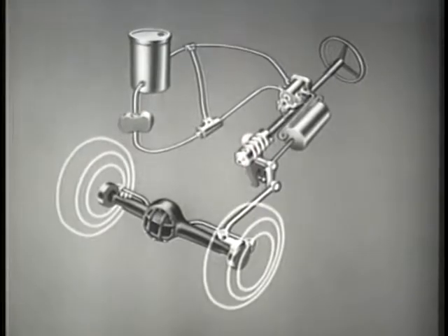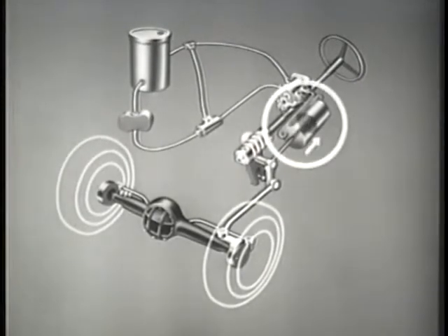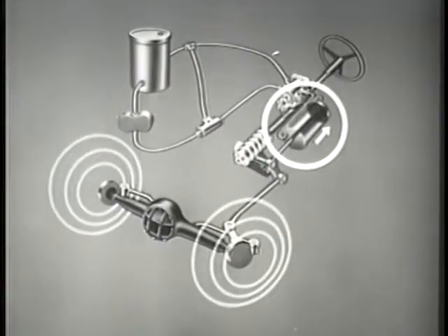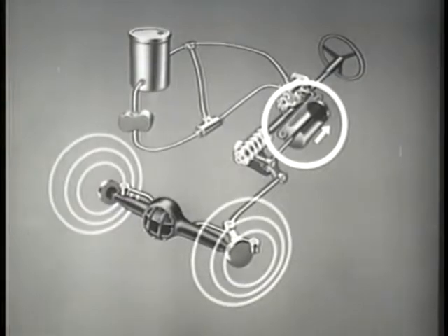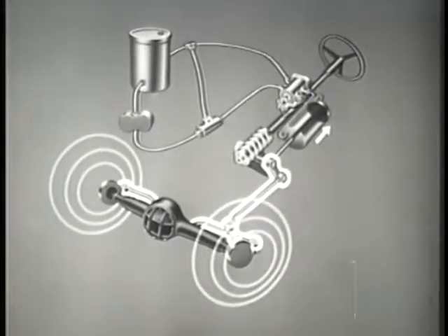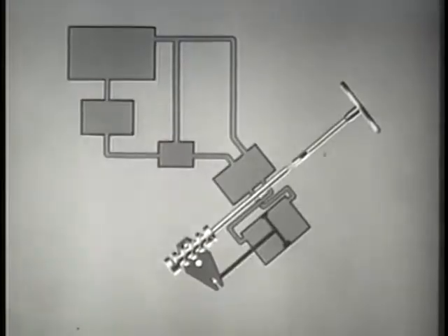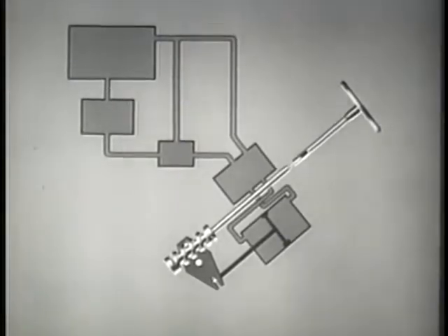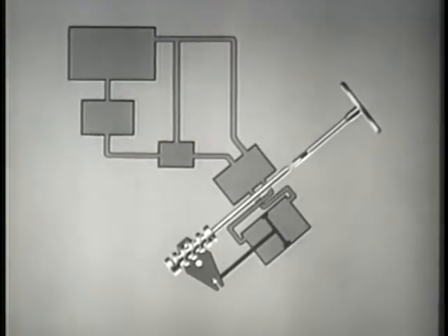In like manner, as the fluid pressure is increased on one side of the piston, it will be moved by pressure differential, aiding in steering the front wheels through the steering linkage. To aid in illustrating the internal function of the hydraulic system, a schematic diagram will be used. The steering linkage from the Pitman arm lever to the front wheels will not be shown.